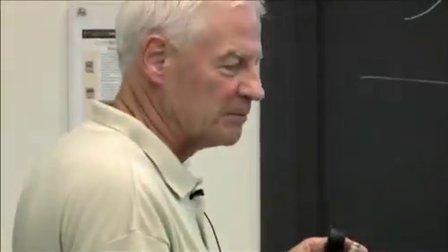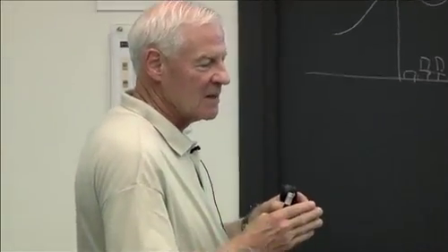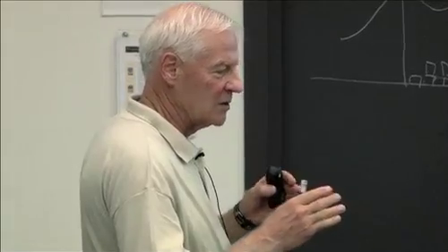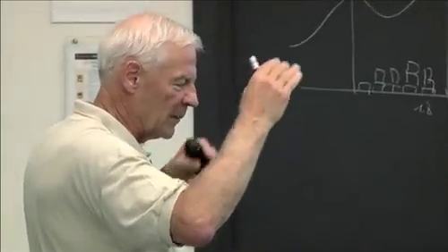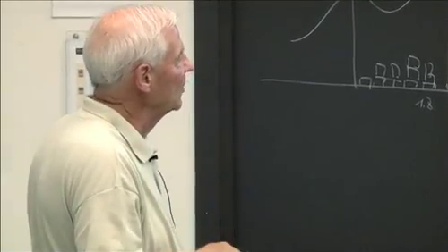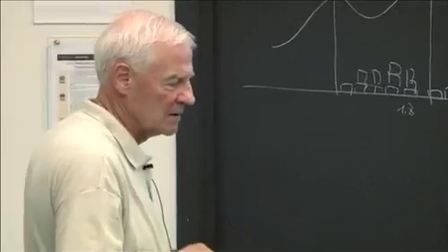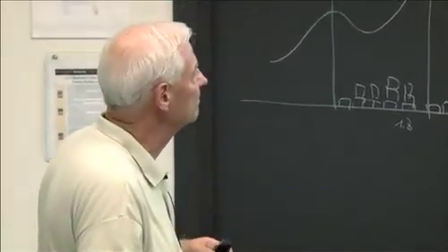So the line shapes depend upon environmental parameters. The line shift depends upon velocity. So you can use the shift to get velocity, you use the shape or the relative heights to get temperature, even when there are different temperatures in the problem. And of course the integrated area would give you something that might have to do with the number density if you could calibrate your fluorescence scheme. So this is a pretty powerful idea.